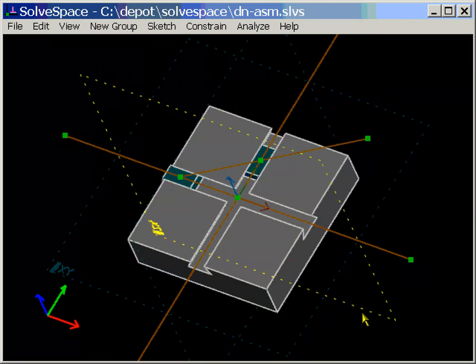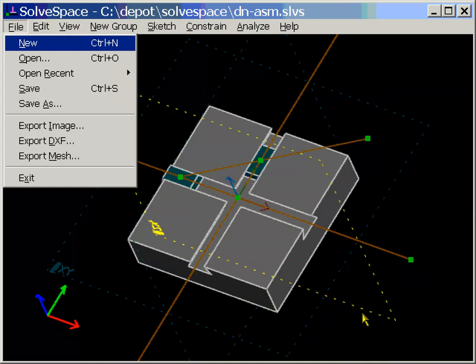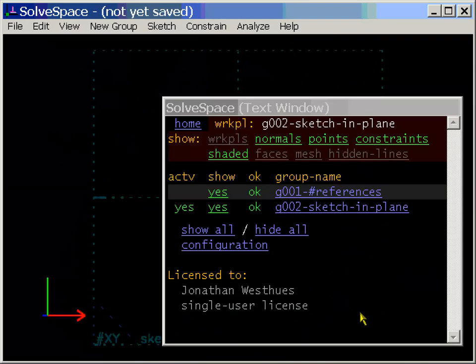So far, when I've dragged a linkage, I've just done it with the mouse. So the trace that I got certainly describes the path that whatever point I was interested in moves through. But the speed along that path was erratic. It was just whatever I happened to do with the mouse. If we're plotting, for example, x versus y, then that doesn't really matter. That just means our points are spaced unevenly. But if we're plotting x versus t, then it means that our plot is meaningless because it depends on how fast I dragged with the mouse, and we don't know that.